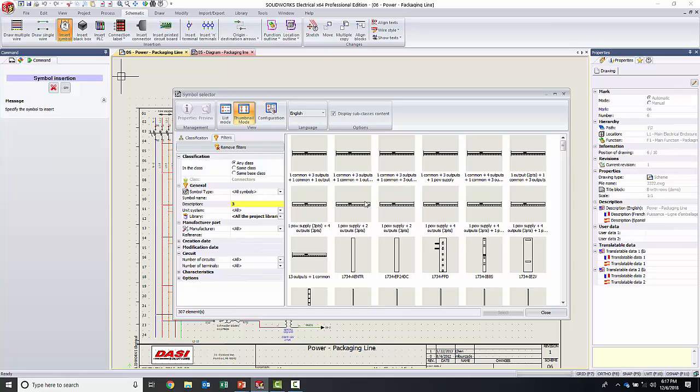You could have SolidWorks build just the board first, give you an outline for you to already work in, because of course you could select and convert the entities into a sketch that would be the board outline. You could have it do that first and then push it to Altium or PCB. And then you could create that schematic, or you could do it concurrently. It's six of one, half a dozen of the other. And it's one of those things that you can push and pull back and forth without too much concern whatsoever. It's actually really cool.